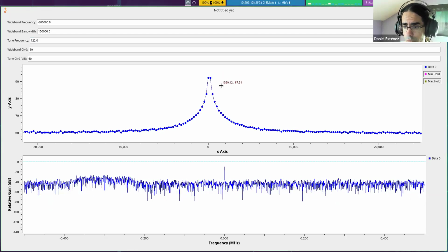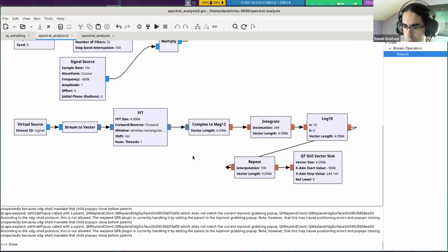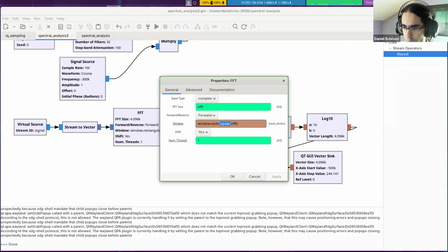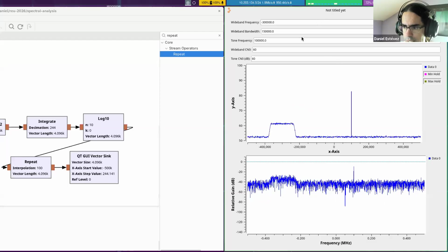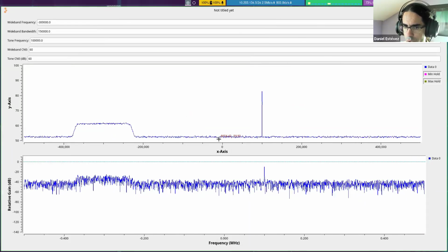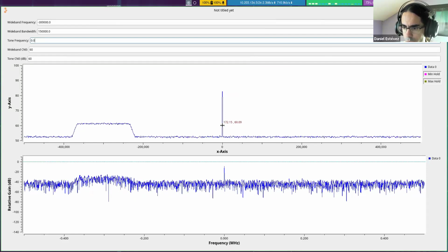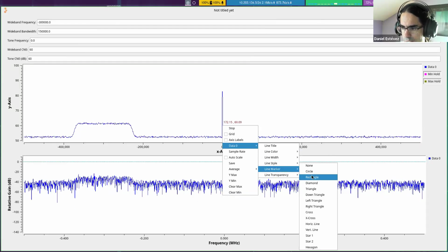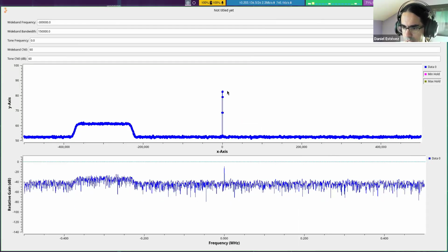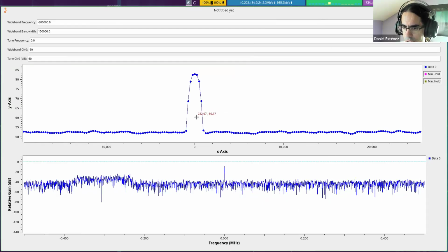So in some cases, you want to optimize for these scalloping losses, and there is something which is called a flat top window that is, for example, used in spectrum analyzers. Because in a spectrum analyzer, you want to measure things accurately, and you don't want to have some losses just because your signal happened to be in between two bins. So I can show you that this window has pretty much no scalloping losses. That is basically how the window is constructed. You ask yourself which vector of numbers would give me pretty much no scalloping losses, and then you end up with that definition of a window.